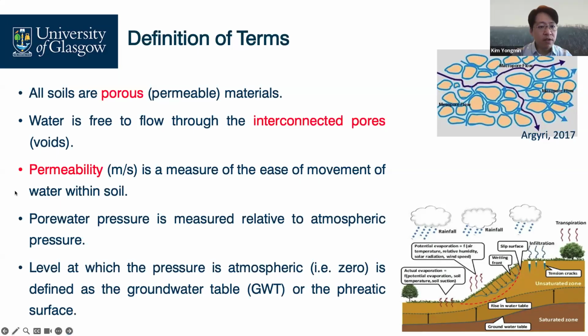And then, in order to quantify the amount of water, we need permeability, which is the flow velocity of water within the soils. Actually, the unit of the permeability of soil is identical to velocity. Meter per second? Yes. Centimeter per second? Millimeter per second? Yes.